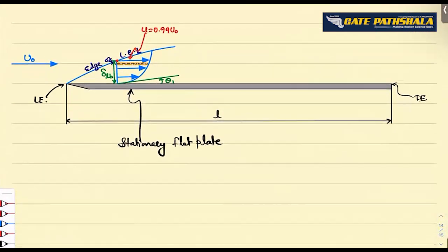Fine. Let's go ahead. So within the laminar boundary layer, one layer is shearing over the other layer. So the structure is a well-defined structure and it is very fragile in nature. Okay. Fragile means kind of delicate, you can say. So what happens is a small change in pressure gradient or heat transfer or due to the surface roughness or waviness, the boundary layer being structurally weak in nature at some particular Reynolds number, which happens at some distance x.